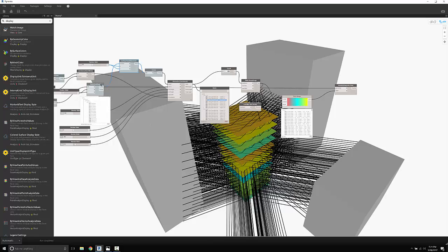That's because it's giving me panels and points there. So that's correct, there's 192 panels, but the key part here is that there's lists of lists of lists of lists coming all the way down, but the color gradient only has a single list. And so that's your clue that things aren't quite right.